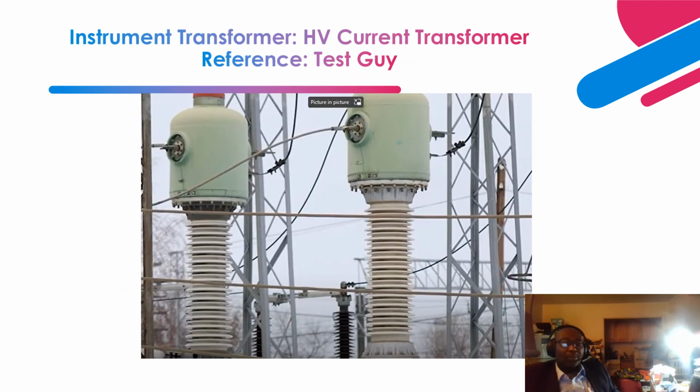Now let's take a look at this substation equipment. It's a current transformer. I've explained to you how this one works. It's connected in series, so you can see the conductors come. The primary conductor goes in here. Single conductor, and inside this you have oil.